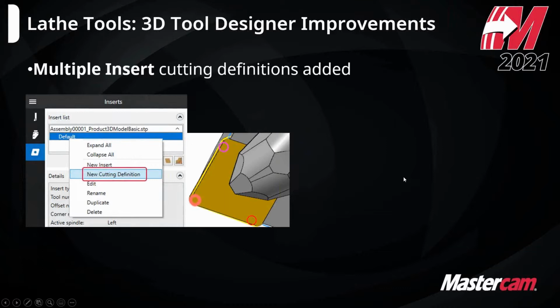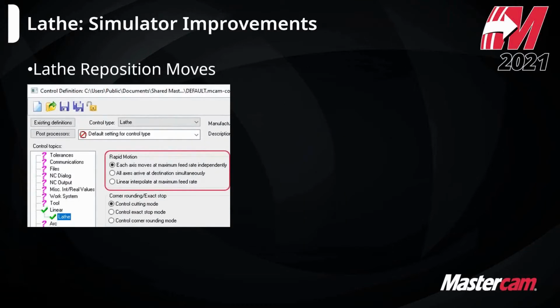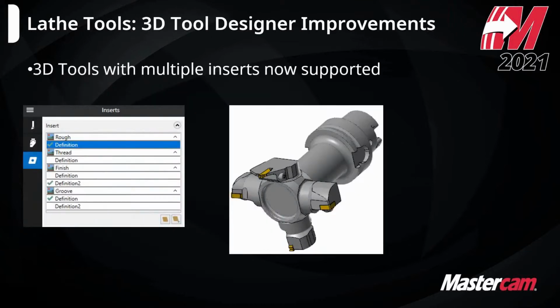We've also improved the lathe simulator. So before, there was a setting kind of buried in the control definition manager, because you would be verifying a part, or it would look good in backplot, and then you would take it to verify. And when it would do a retract or a reposition move, especially on the lathe C-axis group tool pass, it would show that it was wiping through the part. This setting has been fixed, and it now will display properly and verify.